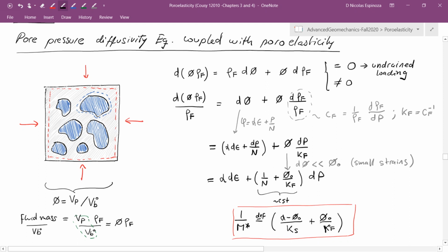Now the fluid is playing a role, because the compressibility of a porous solid, if it is saturated and we do not let the fluid escape, is going to affect the overall bulk modulus. The fluid bulk modulus is going to affect the overall modulus. For example, if I have a porous solid filled with a gas which is very compressible, very likely when I compress it, if I do not let the gas escape, then the bulk modulus of the entire solid is not going to change much.